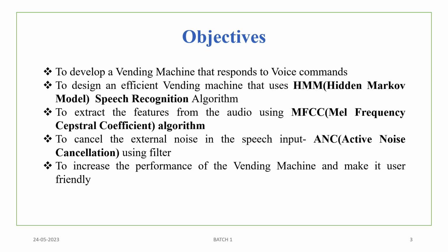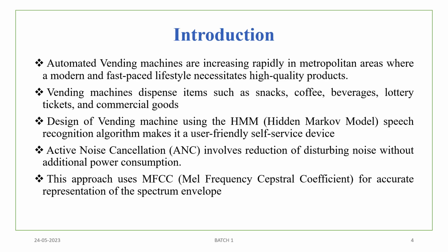The main objectives of our project are to develop a vending machine that responds to voice commands, to design an efficient vending machine that uses Hidden Markov Model speech recognition algorithm, to extract the feature from the audio using MFCC algorithm, to cancel the external noise in the speech input using filter, to increase the performance of the vending machine and make it user-friendly.